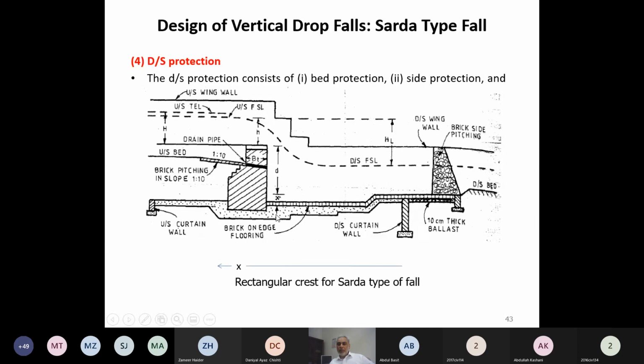So for us, in 2 or 3 steps we will be choosing the x value and calculating the thickness. Over here, maybe after 1 meter or 2 meters of x, we calculate t again and then provide that much thickness. Again we calculate close to over here and then provide thickness over here. That is how the transitions or changes in thickness are visible. Maximum thickness is over here. One option was to provide the same maximum thickness throughout the floor. That would be an uneconomical option. So decide it based upon different lengths and give it a transition.